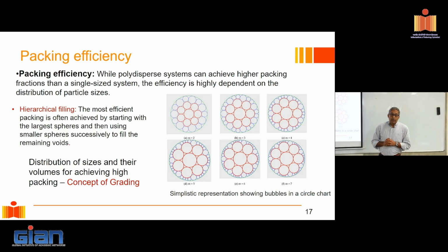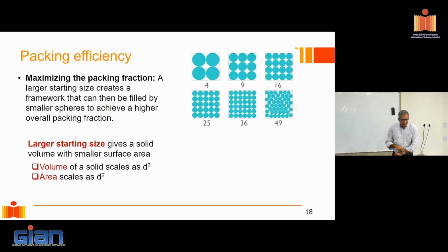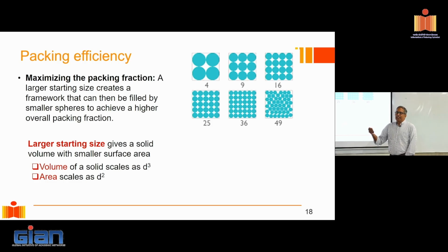Now, a few other things to remember here. When I'm talking about packing efficiency, I'm trying to maximize my aggregate content. When we're dealing with regular concrete, we do not take it to some crazy height. We just try to leave it at some point so that we can minimize the cement content. But when it comes to some of the specialized concretes, like say UHPC, we take it to an extreme where we pay a lot of attention to packing. We pack it down to the micron and submicron scale. Here we restrict ourselves to packing up to perhaps some millimeter level scale.